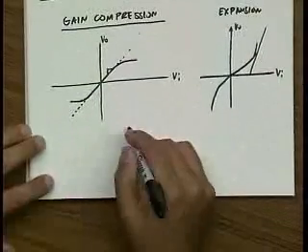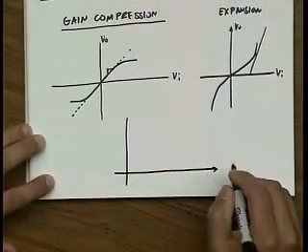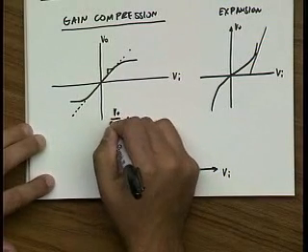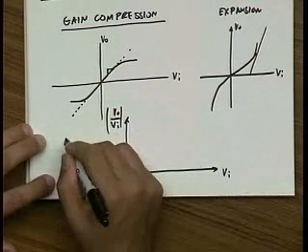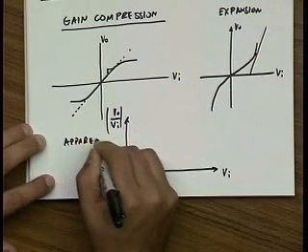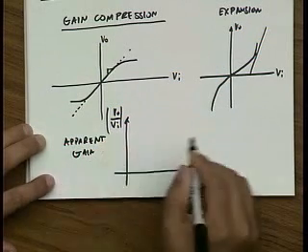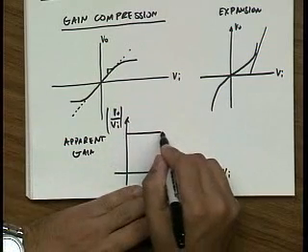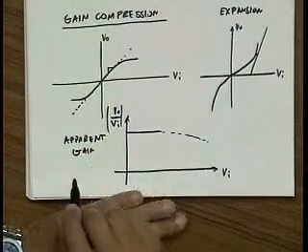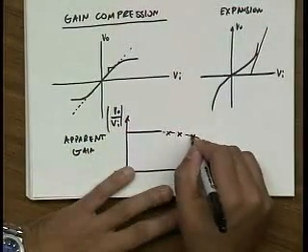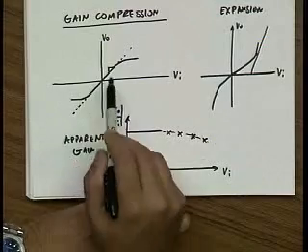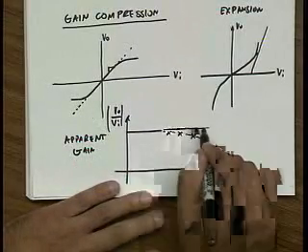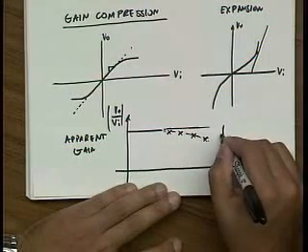So if we look at the apparent gain as a function of the input, let's say this is the input signal, and this is the output signal over the input, we'll call this the apparent gain. Then at low amplitude this will be very constant, but we claim that at high amplitude it'll basically fall. So if we take data points like this, if we look at the input-output relationship from here and just plot it, we find that the gain drops. So this is called gain compression.